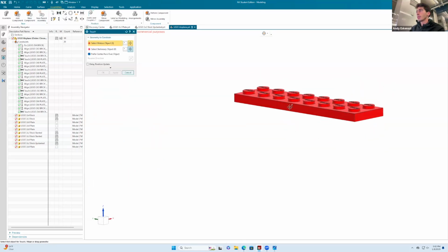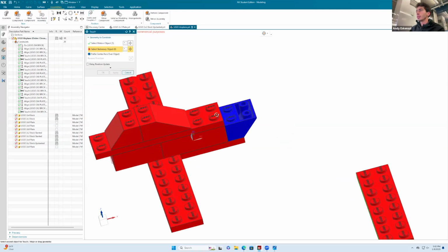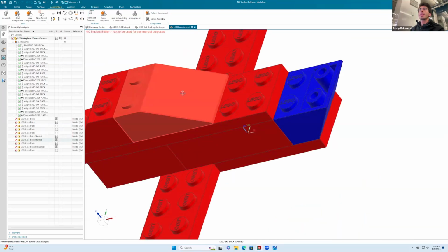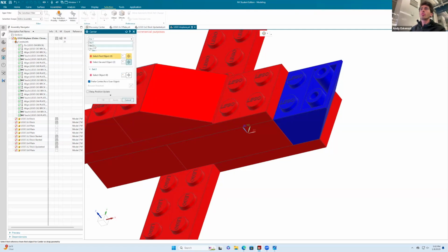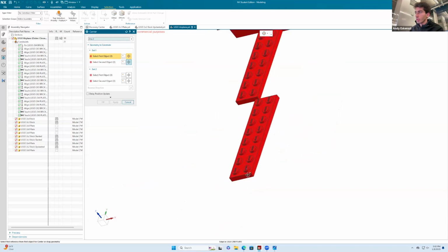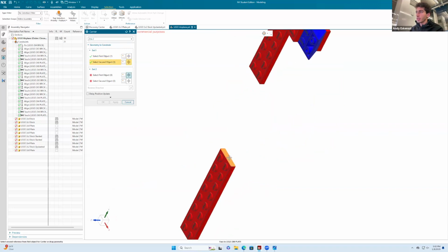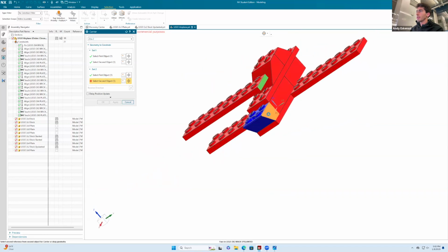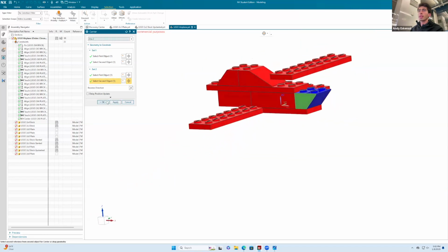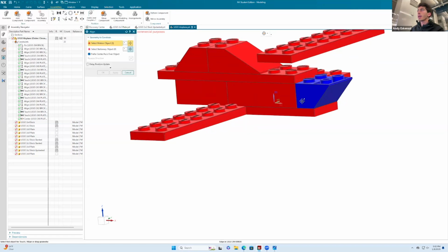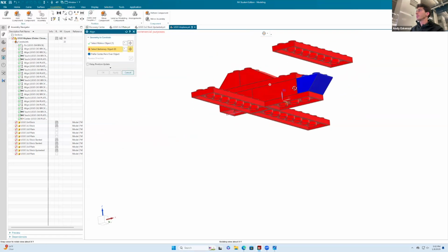So I want this to be touching here. Okay, now there is, I believe it's center, very good. We're going to do two. So I want to align this in the middle. It's an important constraint to use. You select this face, you select that face, and then you select this face, and you select that face, and it brings it all the way like that. Okay. And now back in assemblies, we're going to align, say this face and this face.